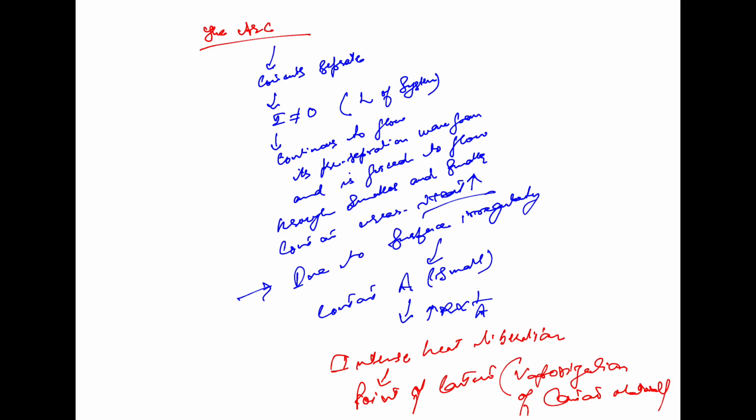And making the establishment of arc easier as the contacts finally part. So what is this arc? This arc actually consists of ions disassociated from the gas molecules. Even you can say that in the oil circuit breaker, oil is decomposed into hydrogen gas, which is an excellent interruption medium. So these are ions disassociated from the gas molecules because of the high temperature and high energy.